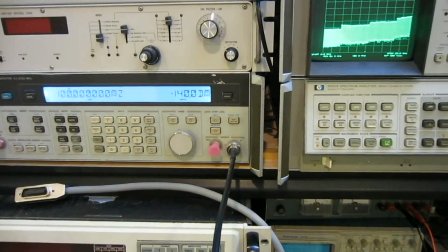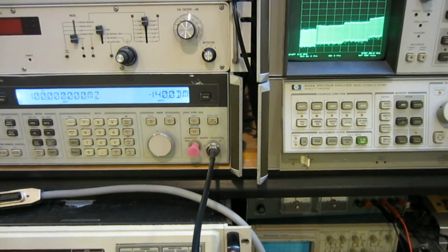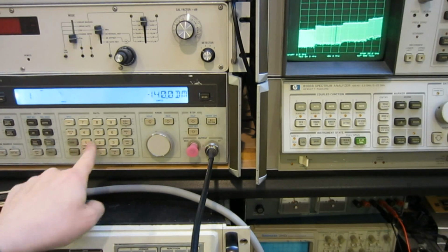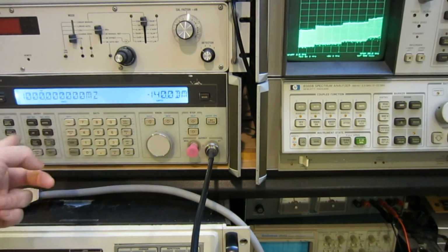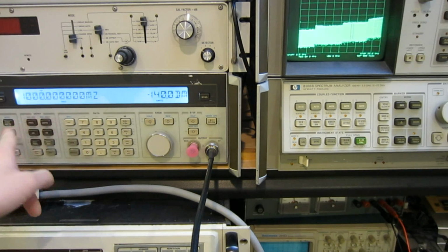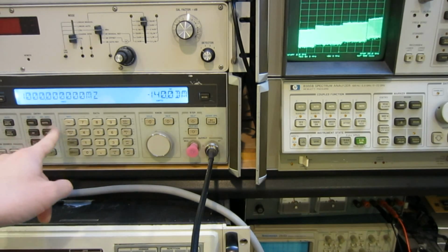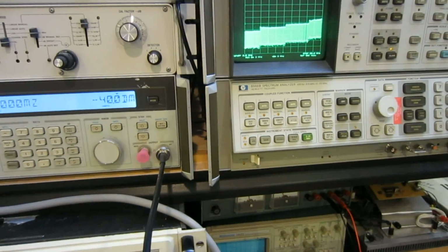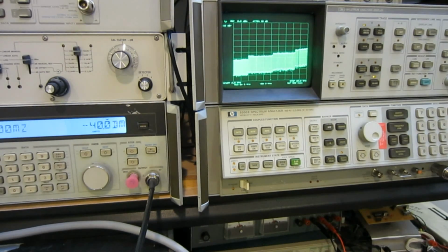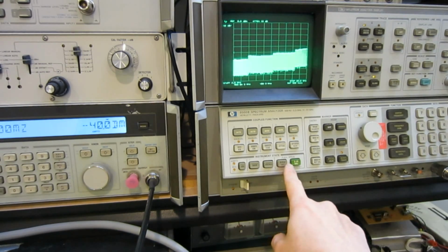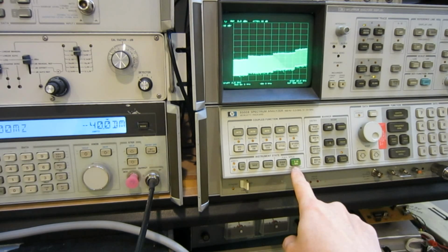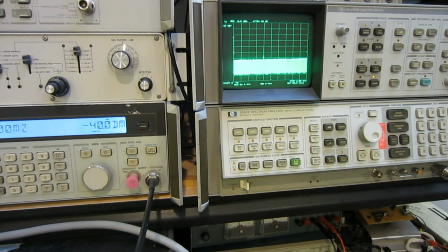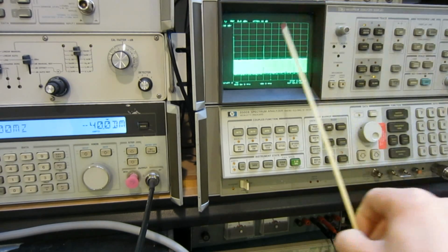Right now we have this N connector cable coming out from the signal generator to our spectrum analyzer input directly. So I'm going to set up a tone from the 8642B right now. Let's say 1 gig. The particular frequency doesn't really matter. I'm just setting up a signal here, and the amplitude, let's say minus 40 dBm. And let's come here to take a look at our spectrum analyzer. Right now we're on the range from 2 to 22 gigahertz, so you can't see the signal. So let's change it back to 0 to 2.5 gigahertz, and you can see that the signal is right here sitting in the middle.